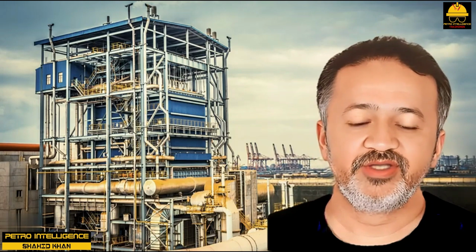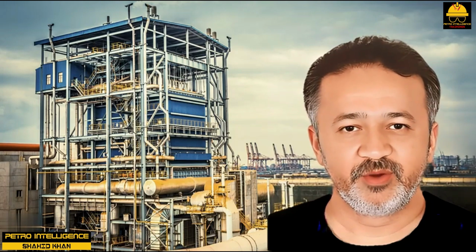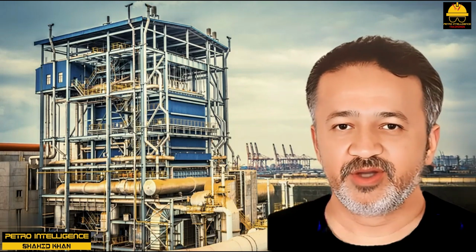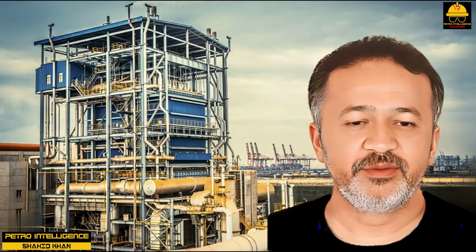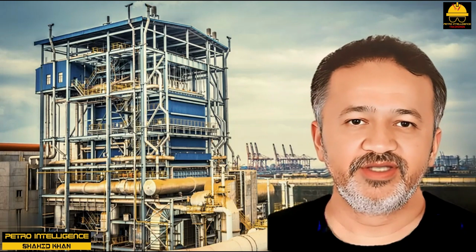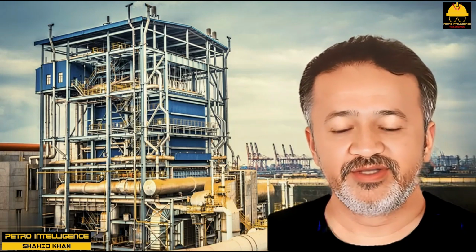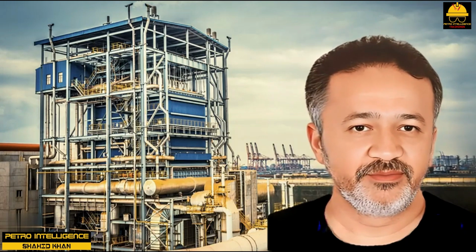The use of wire inserts in fouling service, where extra pressure drop is totally unacceptable, represents poor engineering design practice. This is especially so when the controlling resistance to heat transfer is going to be on the air side of the precondenser cooler.